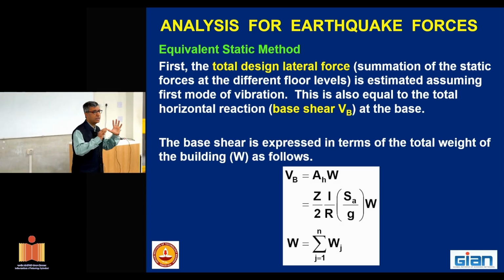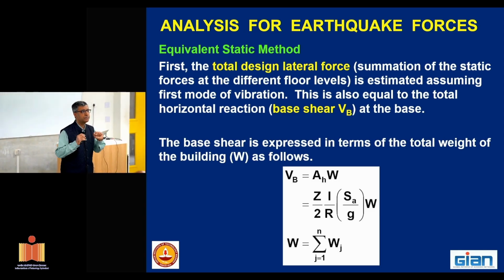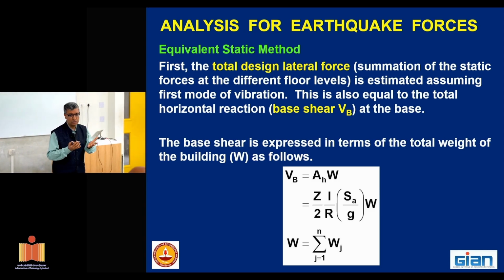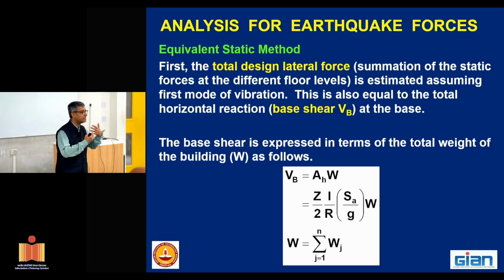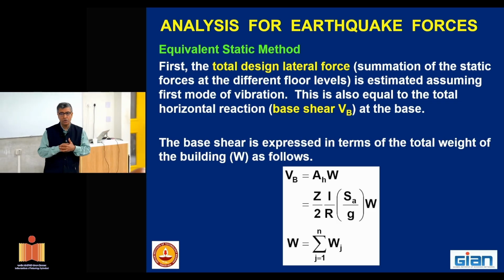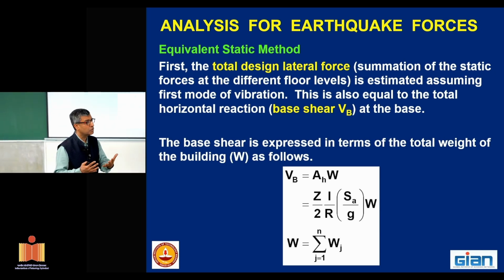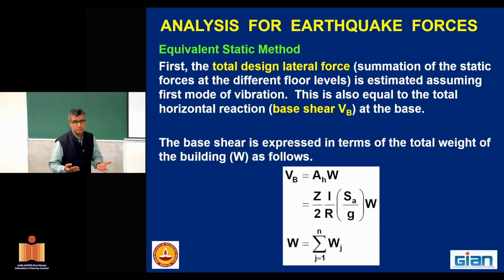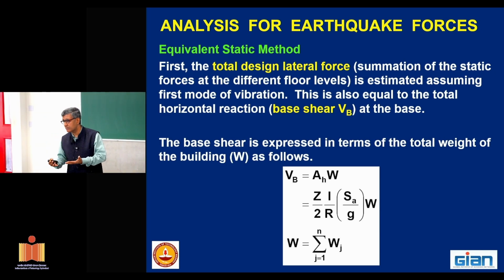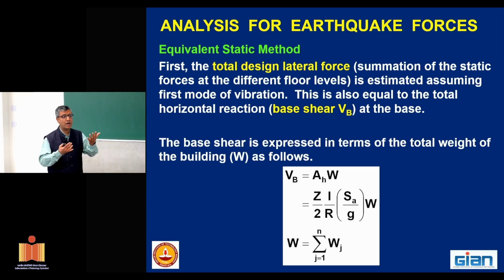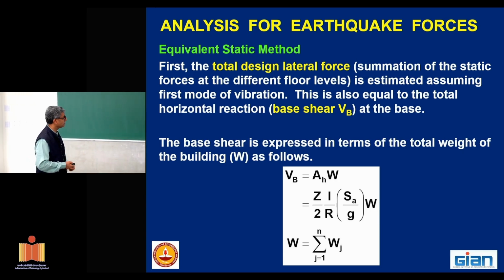And if I have curved buildings, my coefficient comes down and I get some benefit. Okay. For the earthquake, it is the mass of the building which is more important. If I can reduce the mass, then my earthquake force will come down.